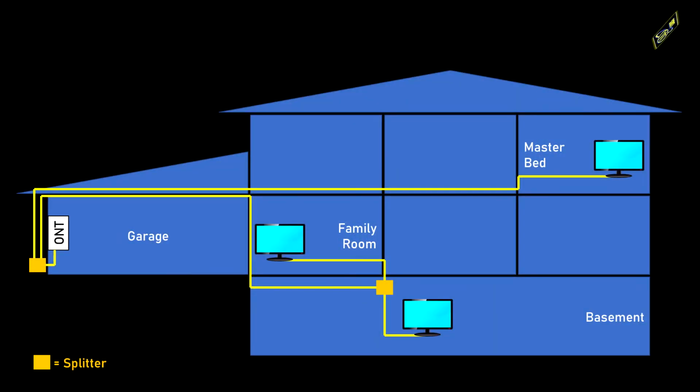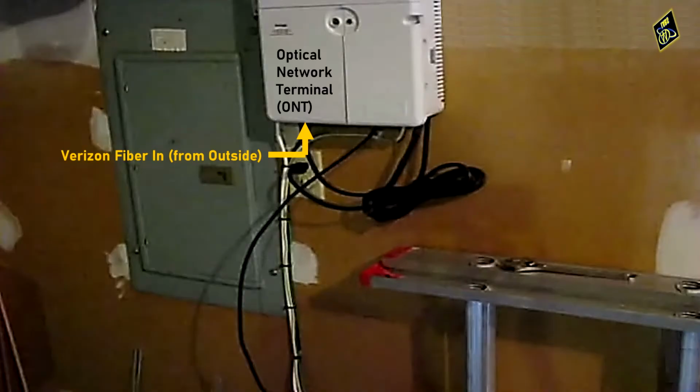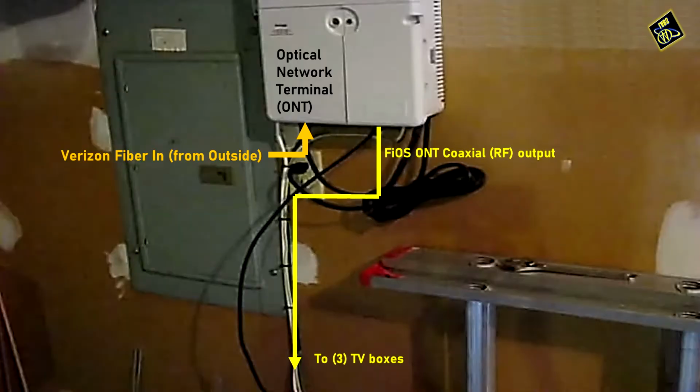An interesting coax interference problem I solved in part with my RTL SDR occurred at my parents' house, where the History channel and a few other channels they subscribed to were pixelating and sometimes not working at all in the basement. Now, they have Verizon Fios, which brings fiber optic cable directly to the home to an ONT, or optical network terminal, and any TV boxes are connected to this ONT via coaxial cable.